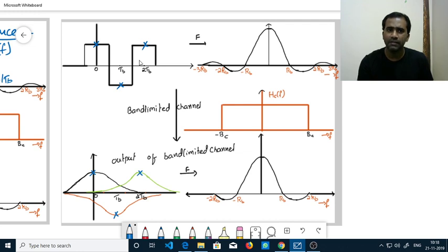Here you should receive, let me say, 5 volts, and let me say this is minus 5 volts. If it is 5 and minus 5 that you are transmitting for the 1 and 0 bit, then why are we taking the cutoff as 0? Because you may not receive 5 volts because of noise. Because of noise, you may receive 6 volts, or 4, 3, 2, 1 volt, minus 1 also sometimes. Similarly, when minus 5 is transmitted, we may not receive exactly minus 5; we may receive minus 4, minus 3, minus 2, minus 1, 0, 1, 2 also. So that's why we are putting some threshold.